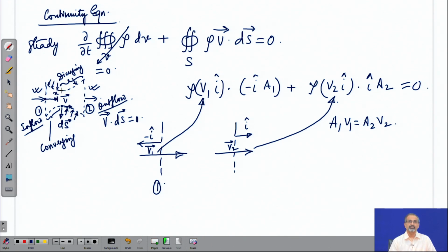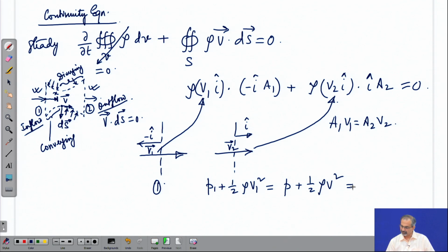At that x location, how do you indicate pressure? You can indicate it this way, that you start from the inflow plane, where by Bernoulli's equation the total sum of the static and dynamic pressure is this, and then at an arbitrary section, it works out like this,